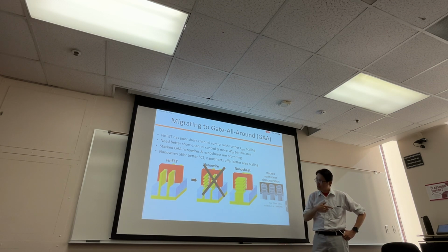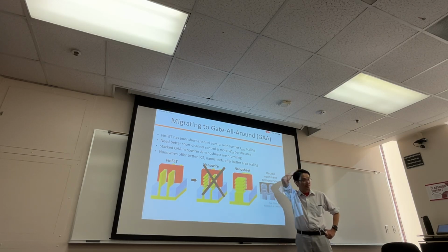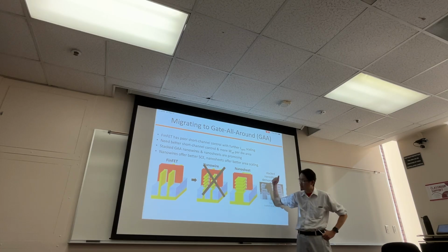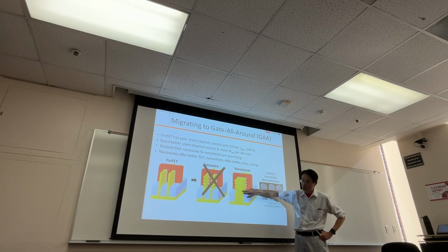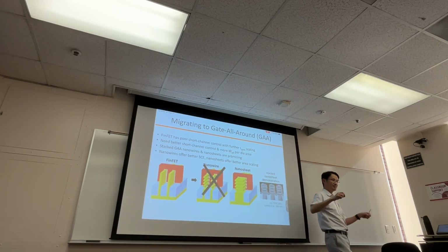By the way, that's one issue. Another issue is, how do we get the drain and source out? That's also another issue, right? Because even if you said there are 4 different transistors, you need to get 4 drain terminals and 4 source terminals. You need to tap them out separately.